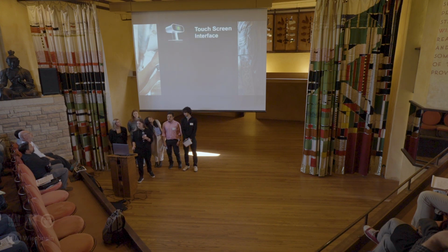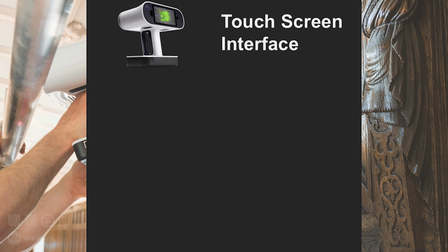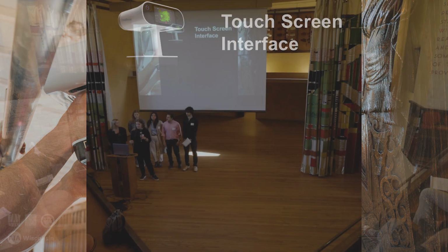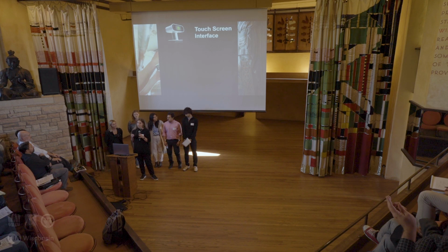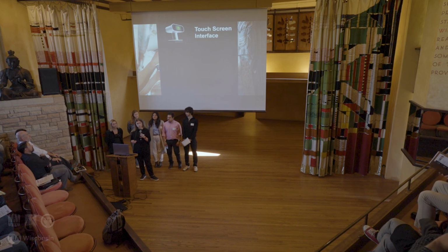All right, but here are some of the key features of the Artec Leo that we find are pretty cool and important. One, it has a touchscreen interface, which is really great. So while you are scanning, you can see your scan in real time. It's really simple to use. You are pointing and shooting. While you are doing that and you see your scan in real time, it lets you know how much you've scanned. So it'll highlight green when you have fully scanned an object, or it will turn red when you need to get more additional detail and information about whatever you are scanning.